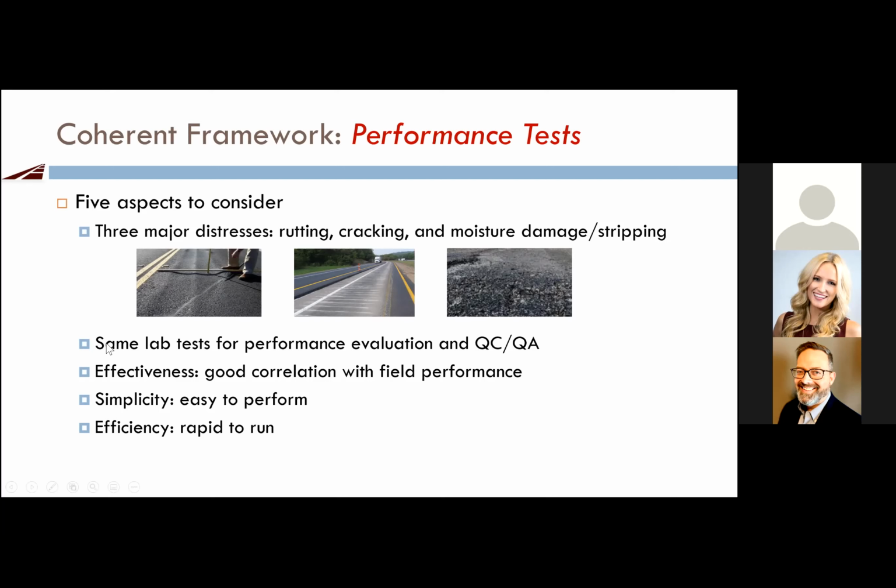The second aspect, we want the same lab test for both performance evaluation and QC/QA. That's very important. In such a way, we can connect these two and become a coherent framework. And we're really talking about effectiveness as well, not just efficiency. We have to make sure any performance test we select or recommend has good correlation with field performance, talking about good performance with cracking, rutting, and moisture damage.